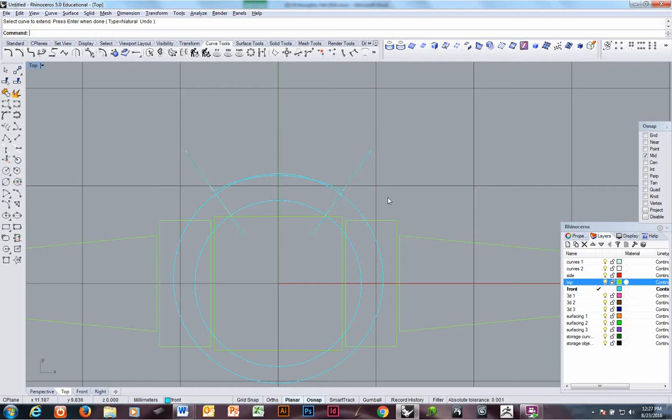Enter when done. Okay, that was easy to do. And it actually kept it a true arc, so I'm all right. But what would often happen is I would get extra control points here. Okay, extensions will often give you a poly curve. So it's usually not elegant math in your curve when you do that. This is fine.